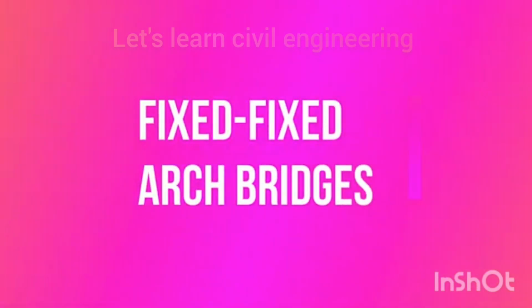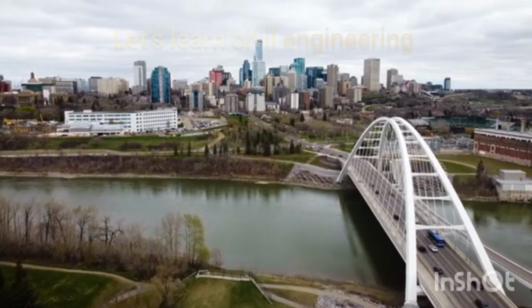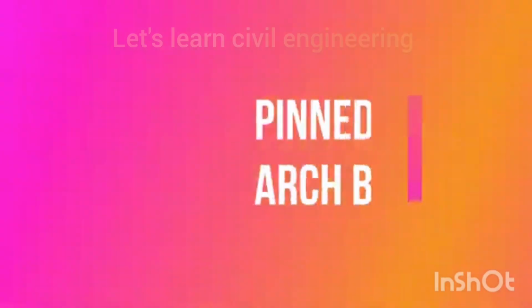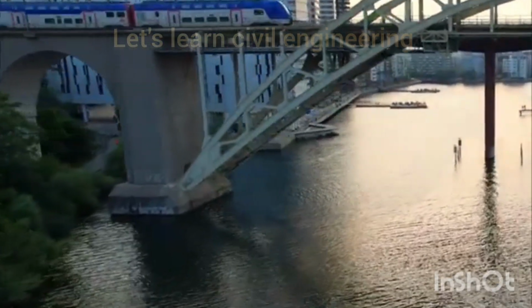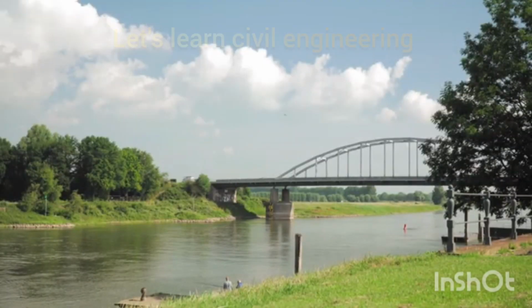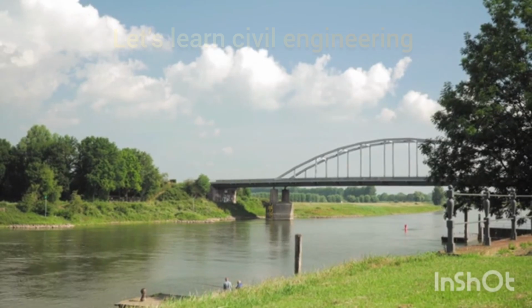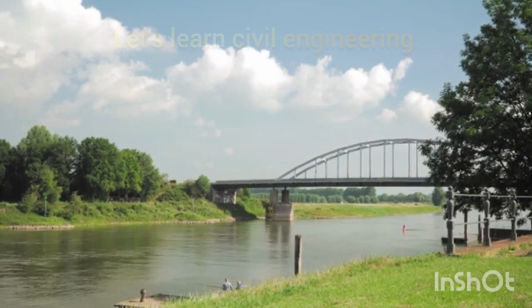Fixed concrete arch. In this type of arch bridge, fixed support is provided at both ends of the arch structure. Pinned concrete arch. In this type of arch bridge, pin support is provided at both ends of the arch structure. Bowstring arch. In this type of arch bridge, additional cables are installed under or on the sides of the deck to tie the arch ends together just like a bowstring.